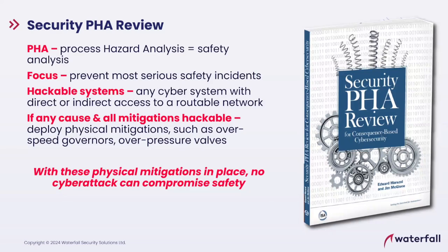And then you've got a column for mitigations saying, well, what stands between normal operation and destruction? What tools have we got in place for protection? One of them is the mechanical overpressure relief valve. Another one is our alarm server. If the operator sees an alarm saying the pressure in the boiler is too high, the operator can turn off the furnace. Another one might be the safety instrumented system that says if the pressure in the boiler is too high, automatically turn off the furnace, turn off the power to the conveyor that sends coal dust into the furnace.